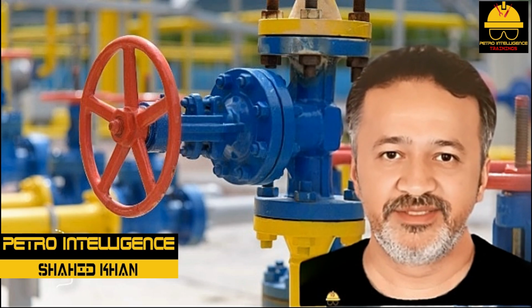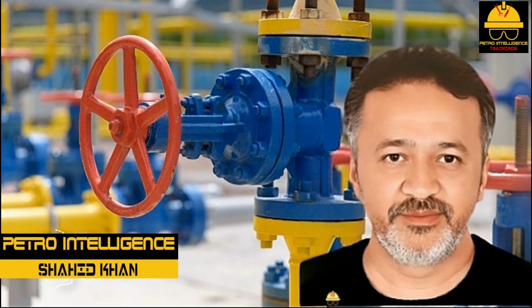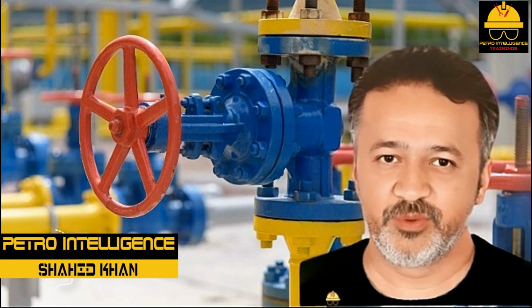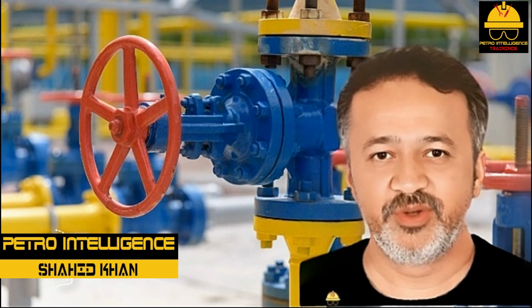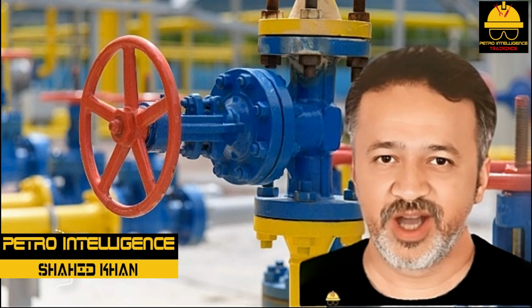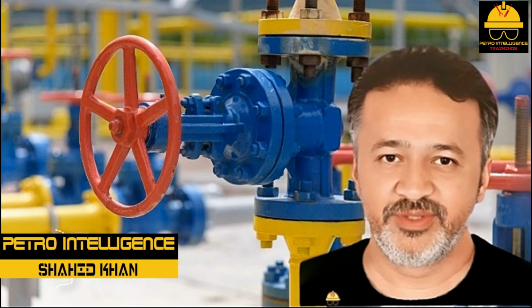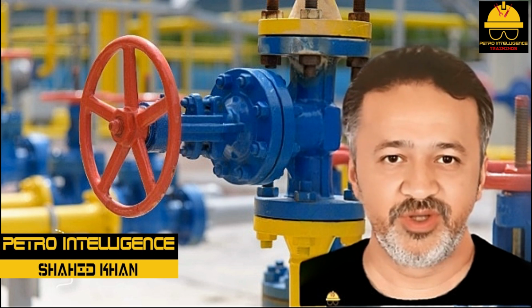Plug valve design. Plug valves come in a variety of shapes and sizes. The plug valve is designed for fuel gas piping systems, low-pressure situations, slurry and lubrication service, on-off service, low-temperature service, and multiport operation. In on-off service, prolonged exposure can damage the seats. In low-temperature service, the seats are made of a plastic-coated material that tends to break down during higher temperatures.